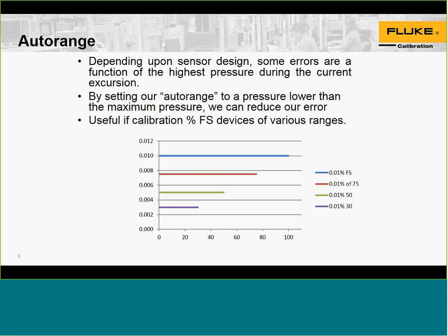The reading for this type of technology is useful because when we were characterizing transducers, we noticed that if you don't take a sensor to its full scale, you could improve hysteresis and essentially improve your precision. So if a calibration at full scale meets the specification, and you only downrange it to 30% and do the same at 30%, you have improved specifications. So you can have that turned down 0.01% down to a lower full scale.